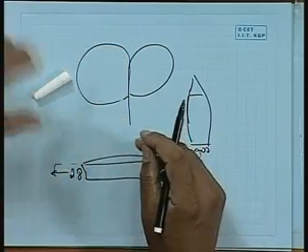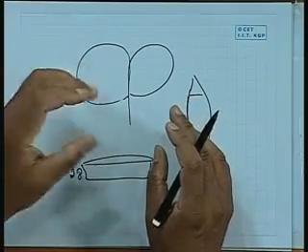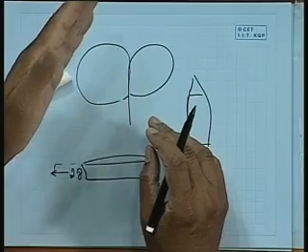In fact, for a torpedo it is so important that you have a counter-rotating propeller, because you don't want any bias. That's why you sometimes must be knowing that zero rudder angle may not be the zero offset. You might have to give some small angle just to offset this. So for a clockwise turning propeller, which one will take a bigger circle? I cannot offhand tell that answer. Let me think: if you have clockwise turning and the ship is this side, then the flow tends to be biased this side. So it depends, you can make out from angle of attack. Most likely the turn will come on the port side.